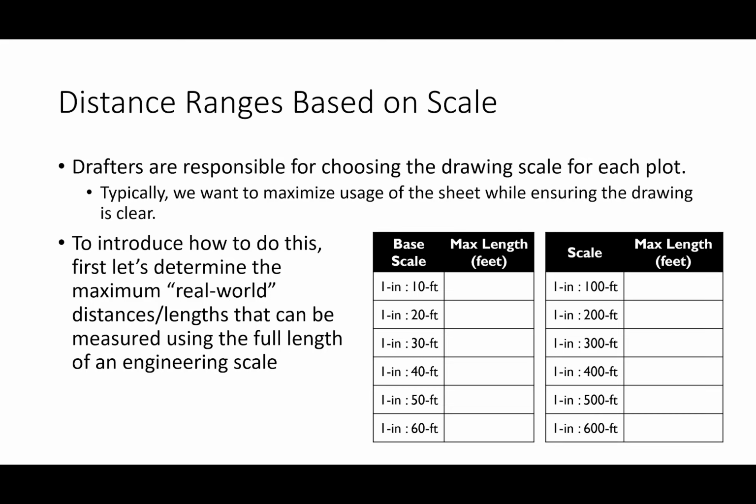Now, to give you an idea of how we would do this, I want to introduce some maximum real-world distances. So let me ask you a question. Everybody follow with me on this. If I had a base scale on a drawing such that 1 inch equals 10 feet, what is the largest real-world distance that I could measure with one of these things? 120 feet. That's exactly right, because this has 12 inches. If 1 inch equals 10 feet, the maximum distance I can measure with one of these things is 120 feet. Everybody with me on that?